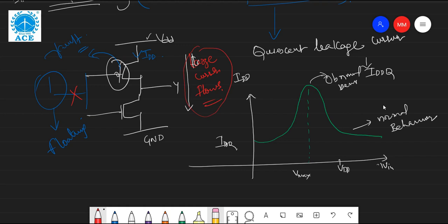When it contains faults, then it happens. Suppose my transistor is off presently, so IDD should not flow here. If there is some fault with this transistor, in CMOS, NMOS or PMOS, this current starts flowing and there is a chance of huge leakage, right? Here we are observing the leakage current: this is a normal value, and this is the abnormal one. This is a large amount flowing.